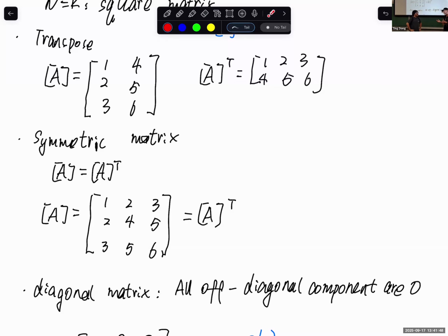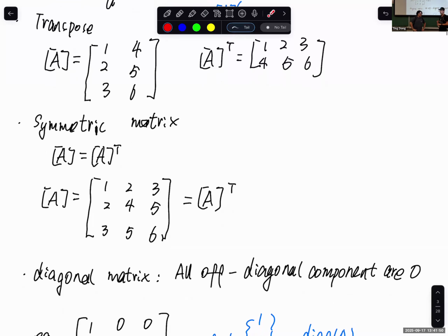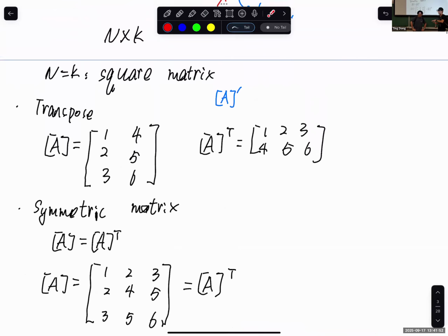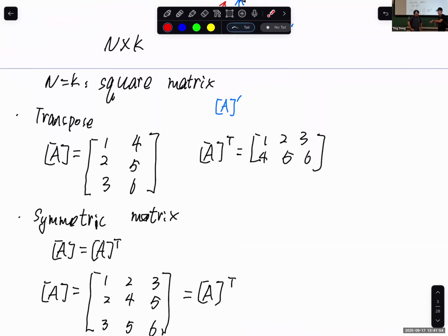Sorry, I have no idea what a displacement field is. So in the 1D bar situation, the stress is always constant in each section. When stress is constant, strain is also constant. And we know that strain is the first derivative of displacement. So since strain and stress are constant, displacement should change linearly.